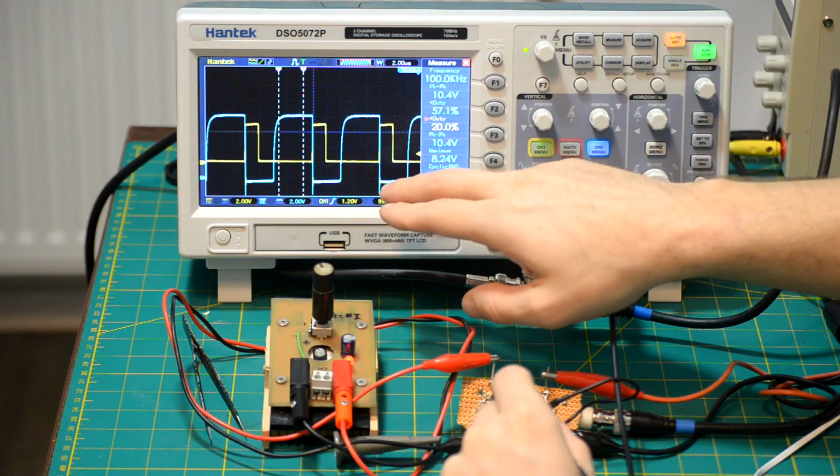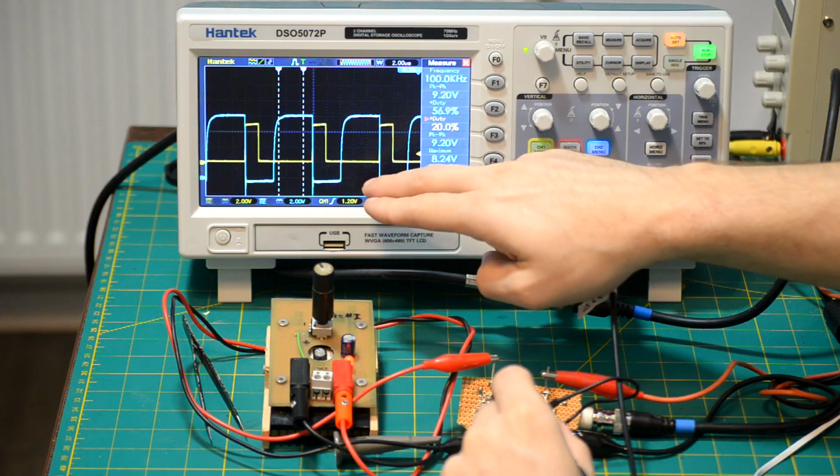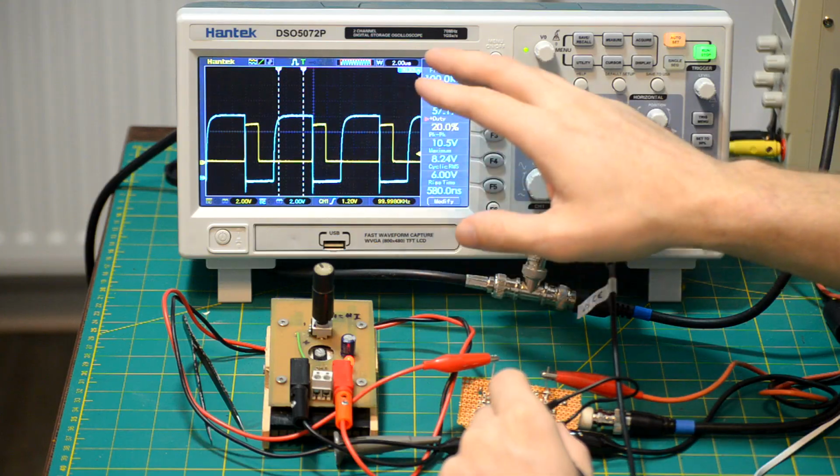And it's important to mention here that the slope at which the transistor turns on, when only the resistor is driving it, is dependent on the capacity of the gate. So if you have a transistor with a very large gate capacitance, then it will have a very slow turn-on slope. If the gate capacitance is very small, then the slope will be much faster.